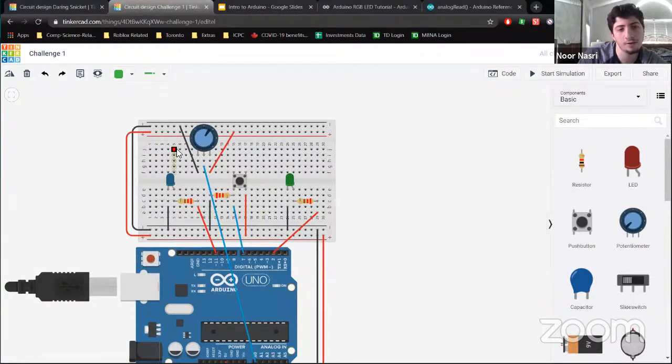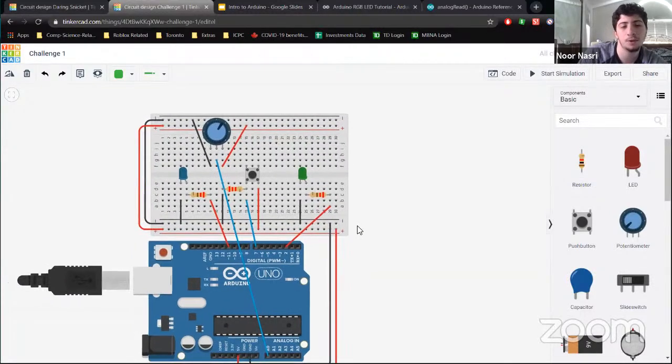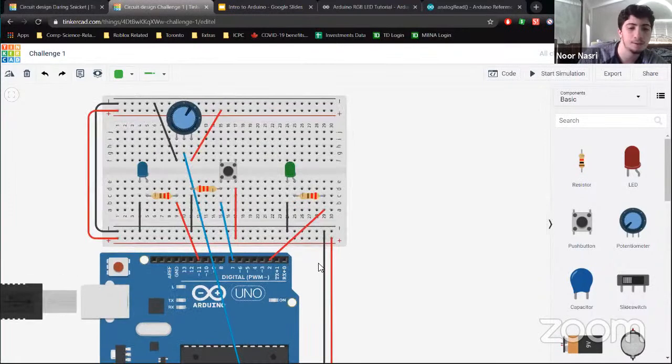And then the ground is the same thing. These two are always connected to ground. The other things that are connected to ground are the things that we're turning on. So we have our own little circuits here. Pin 2 is connecting to the resistor for our first LED, which just gets grounded back into the same circuit. Here, 11 is on a PWM so that we can do analog write. It's connected to this, and again, same resistor, up, down, across the ground.